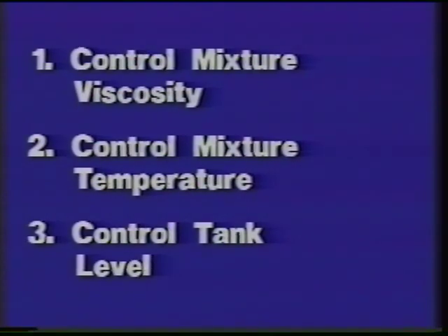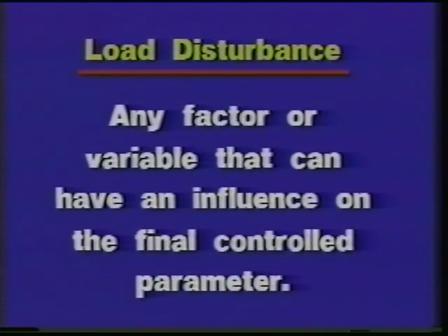Third, control the level in the tank. In the development of these controls, you should remember that all processes are subject to load disturbances. A load disturbance is any factor or variable that can have an influence on the final control parameter. To be able to identify and understand process load disturbances, you must first identify and understand the nature of the various loads on the process, especially as the process becomes more complex or interactive.